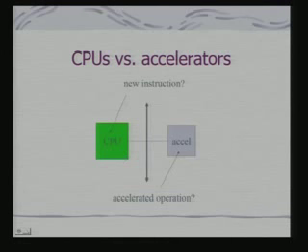If you have a soft core, you would like to modify the CPU, add new instructions and get something done. On the other hand, if you are not having a soft core based platform, you might have a hardcore CPU with programmable logic on the platform. Then you would like to design the accelerator, that means a particular hardware function to accelerate one bottleneck that you have figured out.